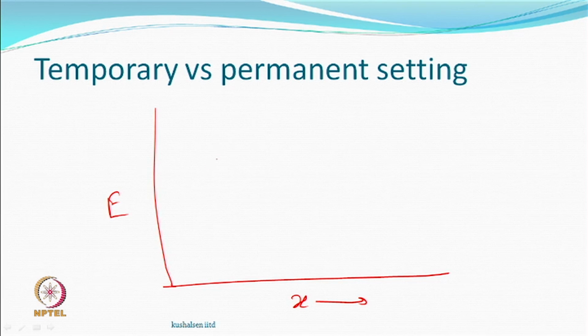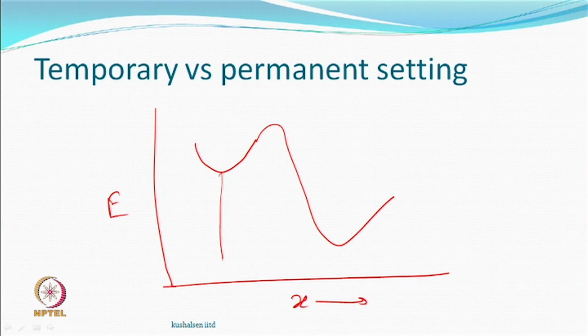So, let us say there was a fiber, it remained the way it is because it is in a stable form. And what do I do? I help it by heating, let us say, and you find thermally induced crystallization taking place or something, maybe disorientation also taking place, and it comes from a state called x1 to a state called x2.